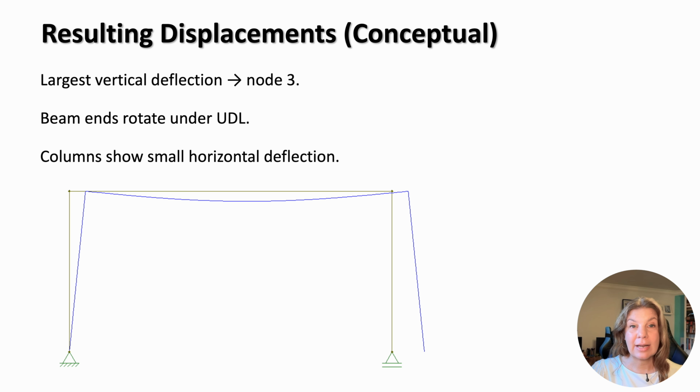The top beam deflects downwards under the uniformly distributed load, with a slightly larger deflection near node 3, where the 20 kN point load acts. Because the left base is pinned and the right base is a roller, the frame also experiences a small horizontal sway to the right. Both columns bend accordingly and produce the characteristic portal frame deformation with downward beam curvature and outward column rotation. This global deformation pattern is fully defined by the displacement vector d and forms the basis for calculating reactions and internal member forces next.